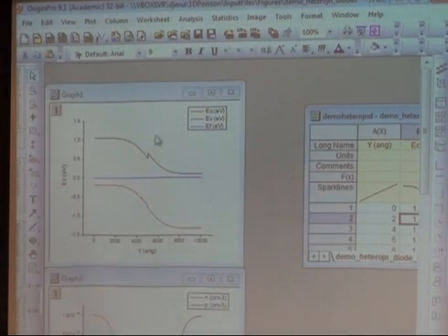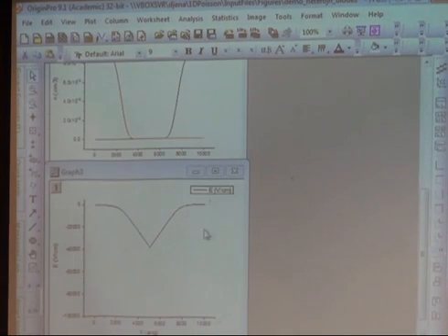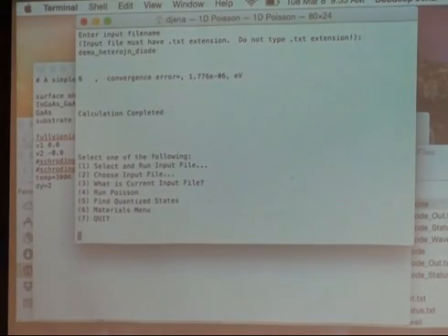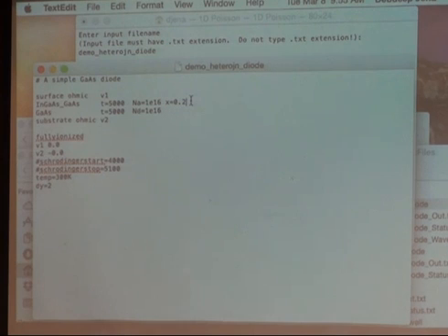So yeah, you can see now the top layer has a slightly smaller band gap, right? You can see the band offset here, delta EC, delta EV. And if you look carefully, there will be a little change in the electric field because the dielectric constants are not exactly the same. It kind of takes care of that. Okay? So that doesn't look too different from a standard homojunction diode, right? But when it starts looking really different is when you increase the band offset or you change the doping. That's when things start looking very different.